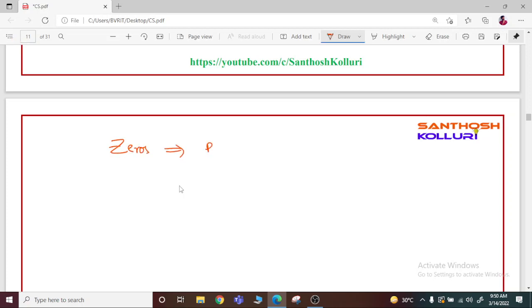So these are nothing but roots of the numerator polynomial, and I am calling the roots of the denominator polynomial poles. So roots of the numerator polynomial can be called zeros, and roots of the denominator polynomial can be called poles. Here the zeros and poles are the critical values of s at which the transfer function P(s) attains extreme values of 0 or infinity.